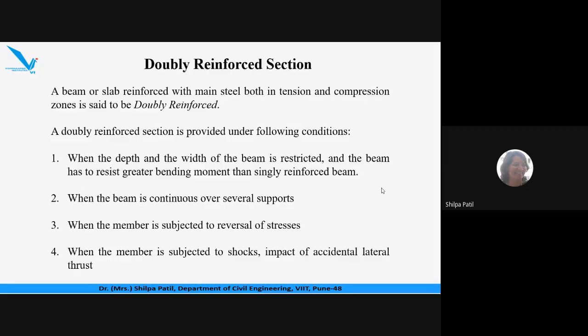If the moment acting on a beam is higher, obviously we have to provide a higher dimension beam, so that the external moment is resisted by the internal forces developed in the section. The internal forces, compression Cu and tension Tu, are calculated based on the dimensions of the beam and the amount of steel provided.